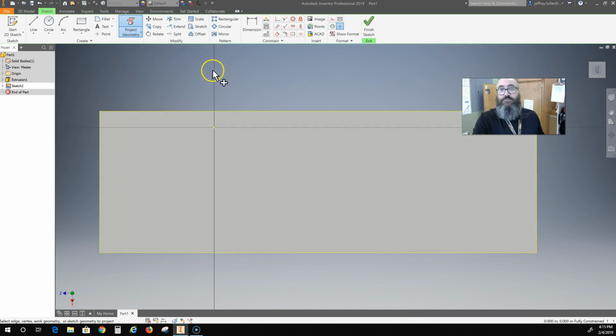And that's really easy, because all I have to do now is click on the Offset button right here, and then come in and click on that yellow projected geometry. And now I can set my mullion thickness, or overall frame thickness. And you can just do it manually, or you can find a thickness that looks good to you.